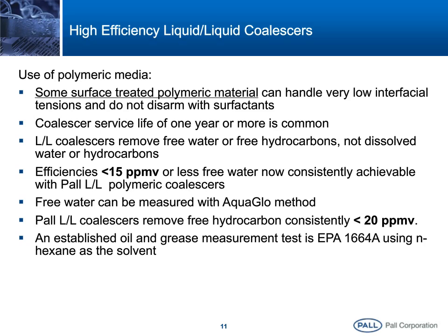Now, it's important to remember that these coalescers remove free water or free hydrocarbons. They don't remove the dissolved water or the dissolved hydrocarbons. In the case of water removal, we can guarantee that these polymeric coalescers will reduce the free water to below 15 parts per million.